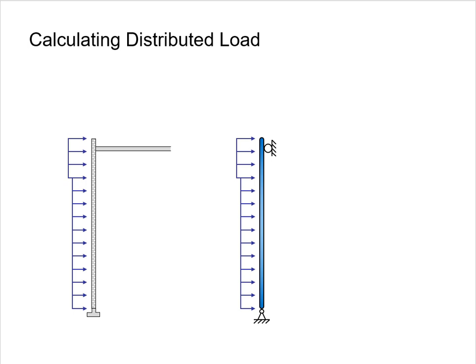If the wall is supported at only the foundation and roof, the idealized wall is determinate. That means we can use equilibrium to find the load being transferred at the roof and at the foundation. If we follow units, the idealized load is distributed, so it has units force per length.